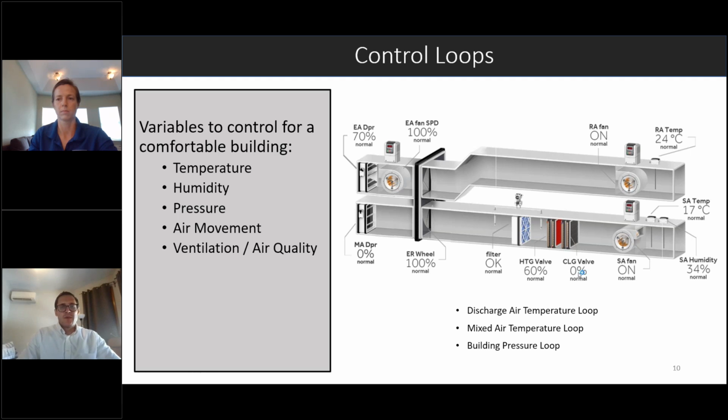And anytime you're bringing in outside air, you're going to usually have to account for some more mechanical cooling or mechanical heating, because that outside air needs to be brought back to the set points that you're looking to work with for the rest of your building. So obviously bringing in that outside air has an impact on the rest of the loops that are operating here. But you can't only account for one thing. You got to account for them all.